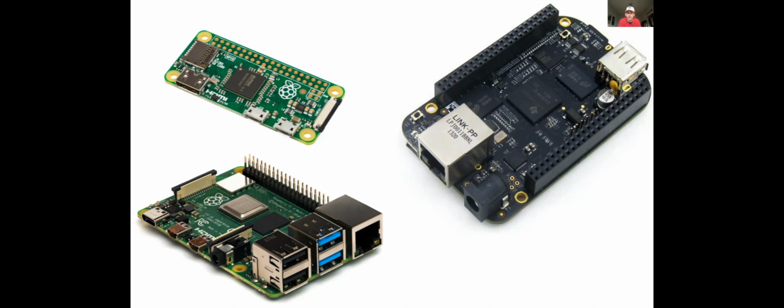And the reason people use these is because they're cheap and they have pretty high compute capabilities. Whereas if you're buying something that's dedicated to space, it's a little bit slower because it's old. So there are a couple of considerations you have to make when choosing your compute platform. First is the architecture.